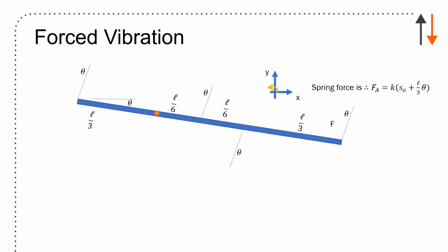And what I want to do is sort of give it a small twist. And so that's what I've done. I've just twisted it a little bit. I've put in theta, and they don't make much sense yet, but they will in a second. I have the reaction force at the pin, By, Bx. And I also have defined my positive directions. Positive is up and to the right.